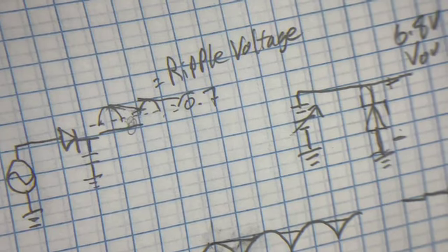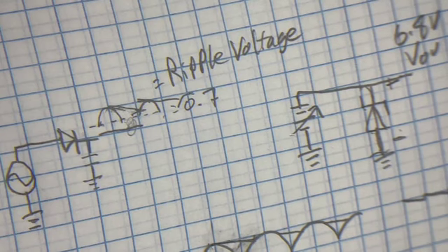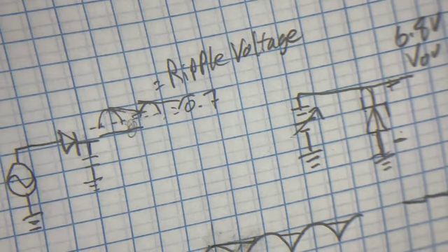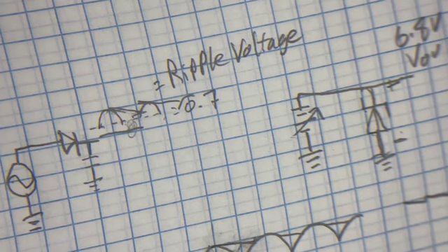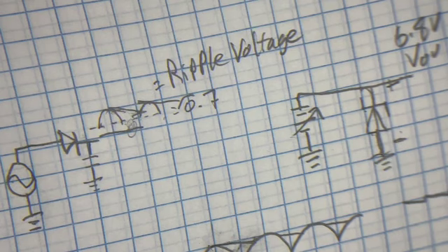And this one will have to be a high impedance. The reason it needs to be a high impedance is because you're setting the current limit for this thing, right? If you don't have a high impedance on there, and this is going essentially straight to ground, this thing is going to try to drive the current as high as it can. So you need to have a high impedance here.